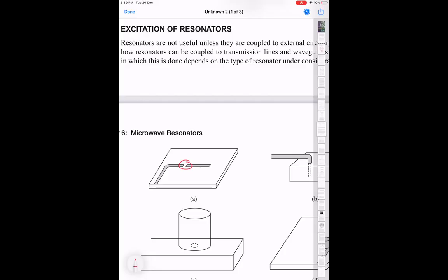This is aluminum. It will have a very different Q factor at room temperature versus at very low temperatures, where in our lab we do our experiments when it becomes superconducting. If this was made out of copper, it will not change so much between room temperature and have a different value. A lot also depends on the surface finish, how the polishing is done, and if there's any contaminants left as well. You can also see how the signal is coming in to this cavity.